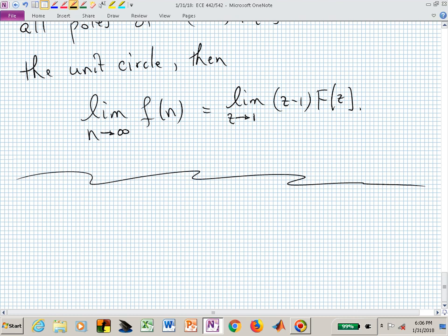When you start shaking that table, it naturally has modes that it wants to shake at, doesn't it? It has natural modes. Those are the poles of your transfer function. But if it's stable, those will decay to zero, and what's going to happen? You'll finally hit a sinusoidal steady state, and that system will just shake at the frequency that you're exciting it at. And what you want to know is, how does that system behave? Does it attenuate or does it amplify that particular frequency when that system is shaken at that particular frequency? And how does it shift in time?